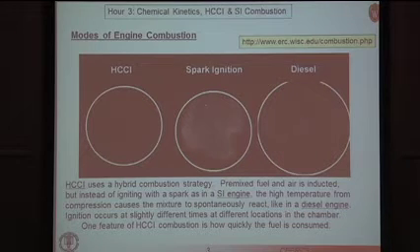HCCI, as I said earlier, you assume that the chamber is homogeneously mixed with fuel and air, and then you compress it, and it ignites, kind of like a diesel engine does. The only difference is that in the diesel engine, the fuel-air mixture is not homogeneous. It is very stratified, as you can see from looking at the pictures here.